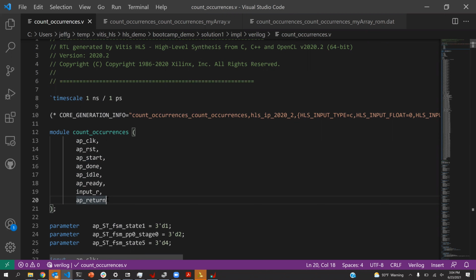What about the hardware modules we looked at on Monday? How did we interface with them from the processor? It was the GPIO block, but how did we talk to it? The processor didn't set a wire to a value. Yeah, it's through the AXI bus. There's a lot of signals, but a bus.